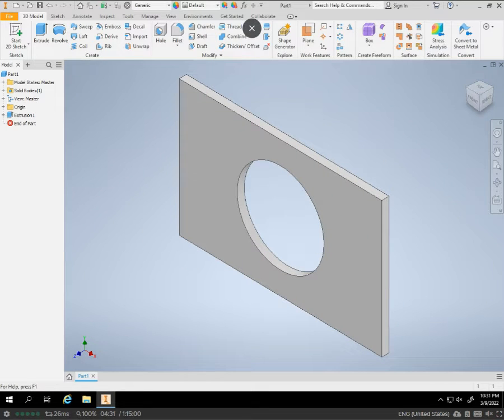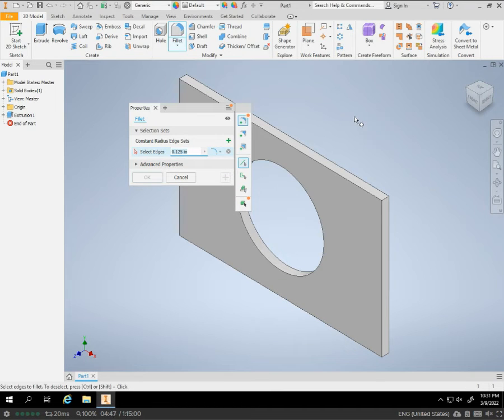All right, so our next step, we're normally going to put another sketch and then start doing something else. But before we do that, this time we're going to use a new tool, which is the fillet. The fillet is going to round the corners and edges like we use fillet in AutoCAD and Revit. You can actually use it in 3D space. So we're going to set the radius to 1, and then we're just simply going to select the corner edges of these. So make sure that you're selecting the corners and not the flat edges.